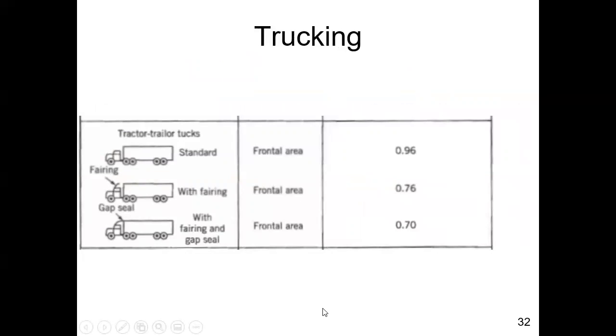And then we talked about trucking, and in this case, this spoiler at the top is known as fairing. And you'll notice this one has a gap and this one does not. Before, what I showed you was fairing on the back, and then there is fairing that you can actually put underneath. But again, what these do is decrease the drag coefficient, which again, just putting on that spoiler on the front, the fairing on the front, 21%.